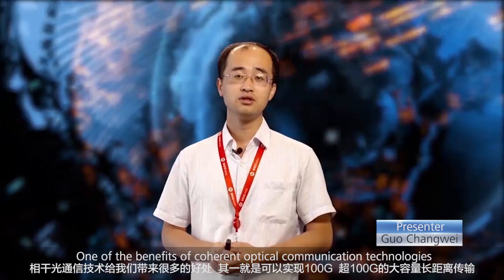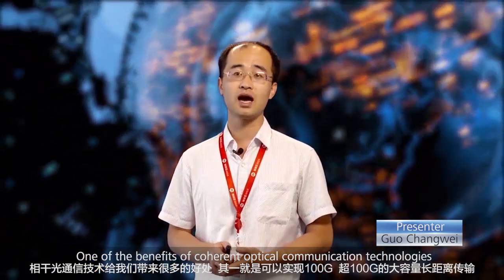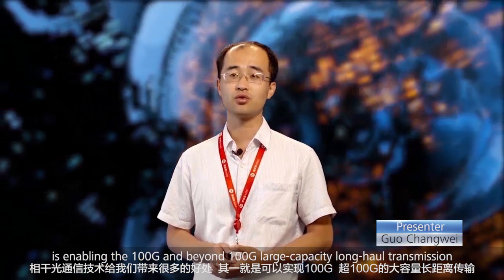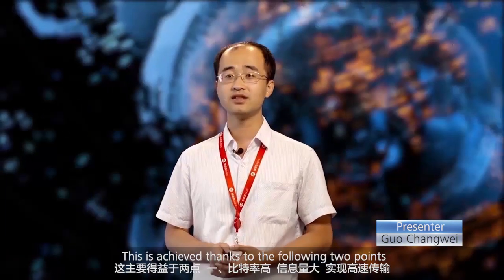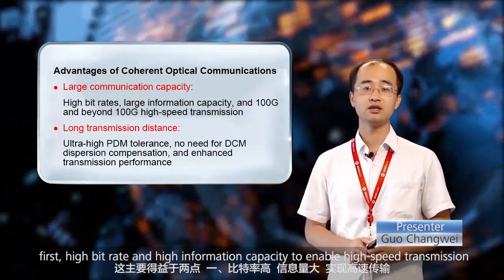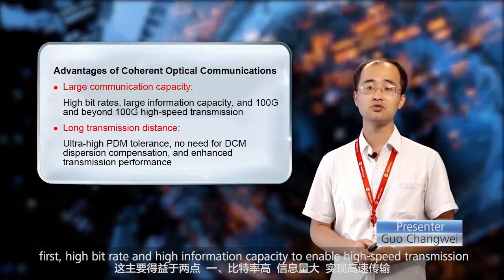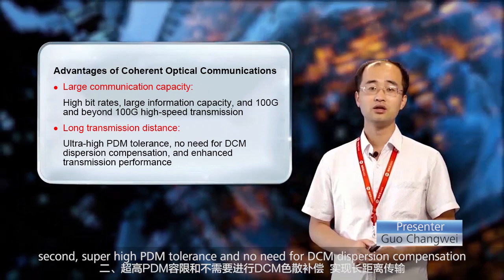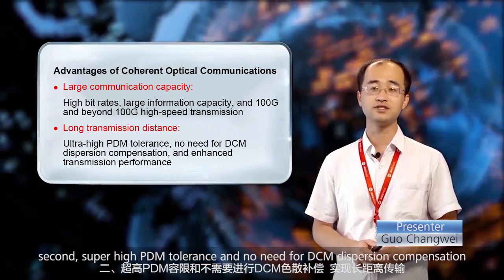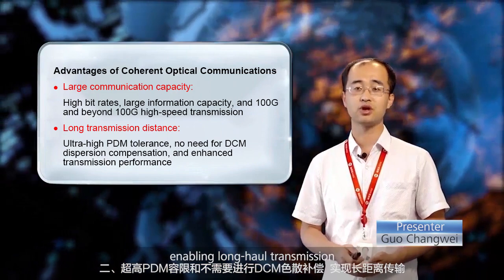One of the benefits of coherent optical communication technologies is enabling the 100G and beyond 100G large capacity long-haul transmission. This is achieved thanks to the following 2 points. First, high bit rate and high information capacity to enable high-speed transmission. Second, super high polarization division multiplexing tolerance and no need for DCM dispersion compensation, enabling long-haul transmission.